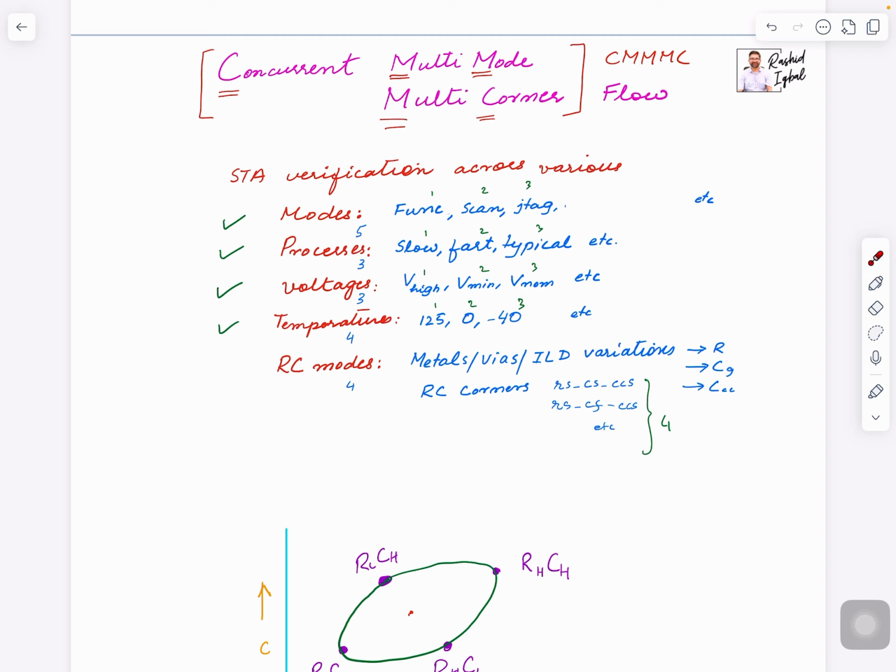I'm seeing right now in the low technology nodes a lot of RC interconnect corners. We used to have just one purely process-wise. This is process, and then based on different temperature, because different temperature can have different resistances, we extract one for a high temperature and one at a lower temperature, so we have min and max PEF.